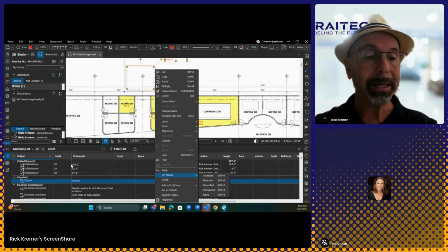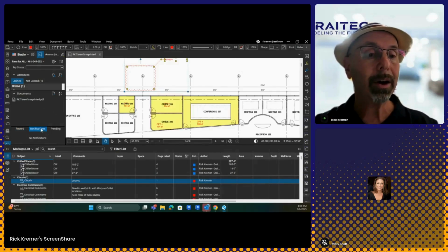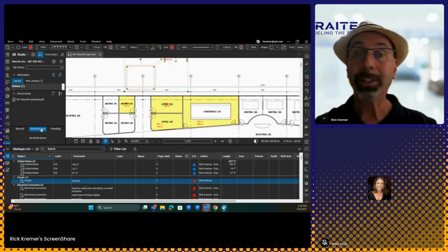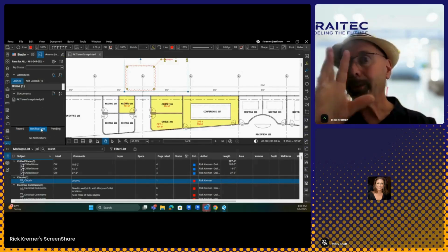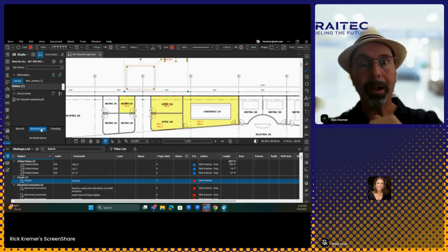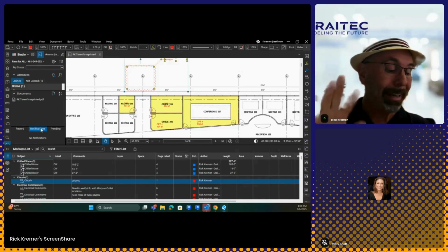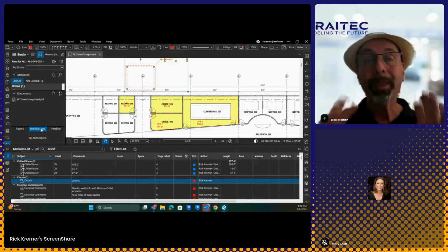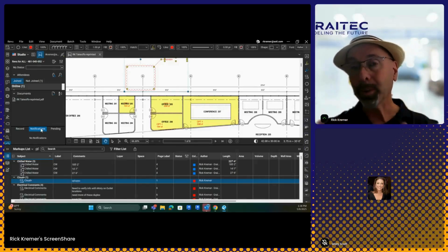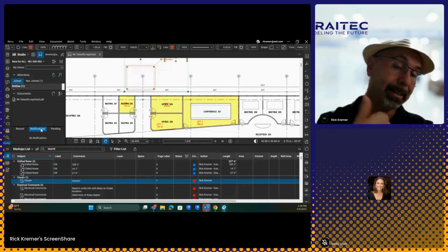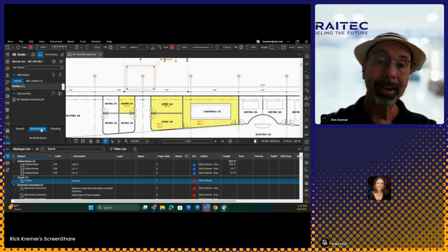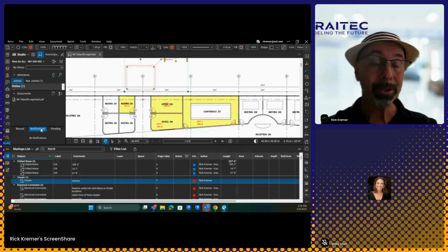So you can cover your bases, as well as here on her screen under notifications, if she has review on, it'll start flashing like a disco ball. Anyway, that's it. I just wanted to tease you all and introduce you to the 3 most common used tools in Bluebeam so that you can get up and running quickly. And that is measuring areas, linear calculations, creating markups, customizing them into your tool chest, and then collaborating with others.